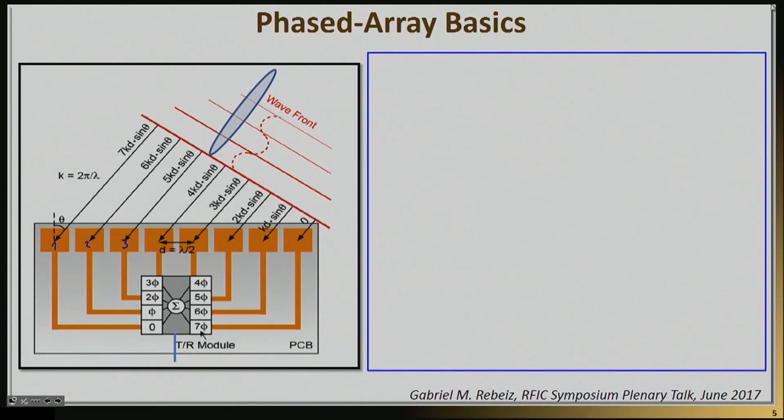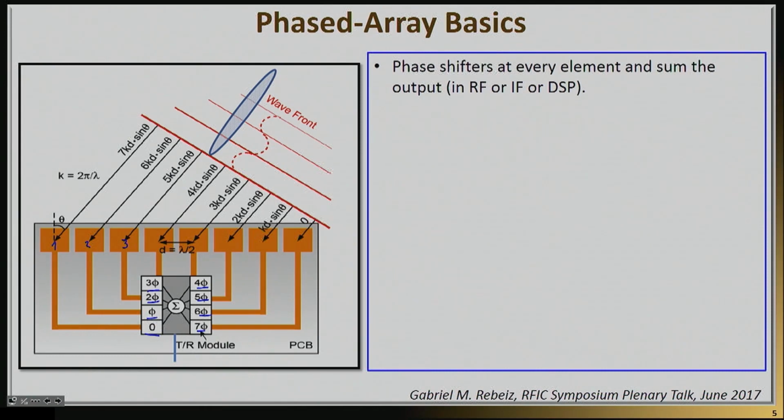These antennas are shown here as patch antennas, but they can be any type of antennas. If you can put these antennas together, and control the phase that you're feeding them with, you can coherently add the signals. It's that simple of an idea. When you coherently add the signals, you gain a very sharp beam width, much sharper than each antenna would give you by itself. So you need to include phase shifters, shown schematically here, that control the phase of each antenna element. And that's true both for transmit and receive.